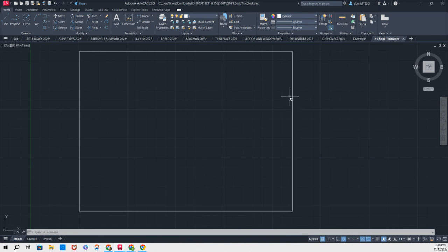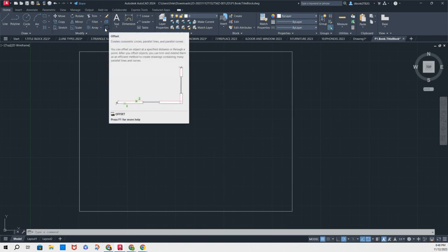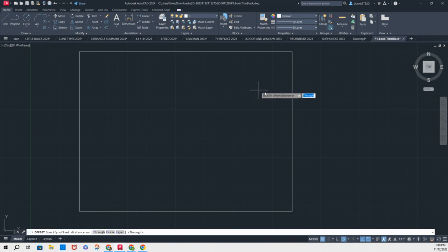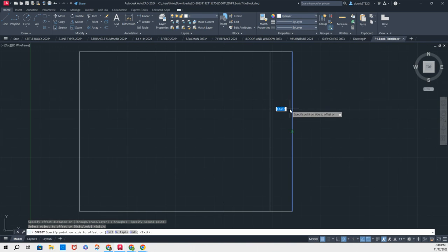The next thing that you're going to do is use this existing line to make two lower parallel lines to it with an offset command. This is a tool that's used consistently all the time. So if you hover over it, you see that there's this offset menu control explanation that comes up. I'm just going to click it. It's weird because you have to click the line usually 3 times before it starts to work. At the beginning of this, you don't really need to know any more than that it's just going to take you a few clicks before you get this line.